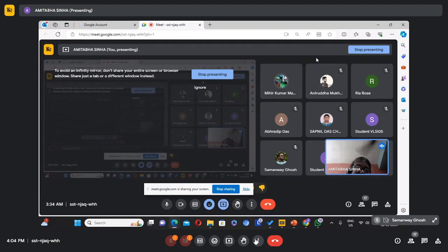From a single device, don't always expect that it will give you the extreme, because ultimately your speed will be limited by the speed of the velocity of light. You cannot reach that. So whenever we are thinking of enhancing the speed, we are devising many other techniques. Suppose the frequency bandwidth of the signal is 25 gigahertz, then sampling rate must be twice of that. That is all right. What I said is something else. I said that you use multiple samplers and enhance the speed.